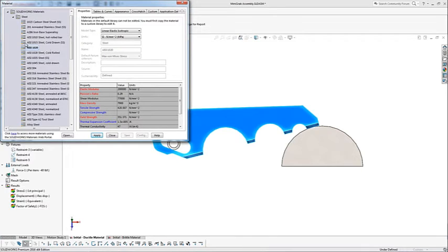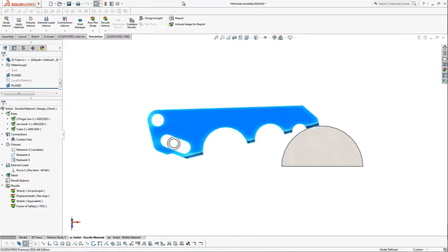For the ductile material, we're going to assume that it's a steel 1020. We can see we've got our yield strength defined. Here's our tensile strength. No tensile ultimate strength, no compressive ultimate strength. There's a great section in the SOLIDWORKS Simulation Step-Up series that's already been done that deals with material property definition. There's a lot here in material properties, including that SS does not mean structural steel or stainless steel. It means there's a post-yield stress-strain curve defined. So if you want to do a nonlinear analysis, lots of different things are available.